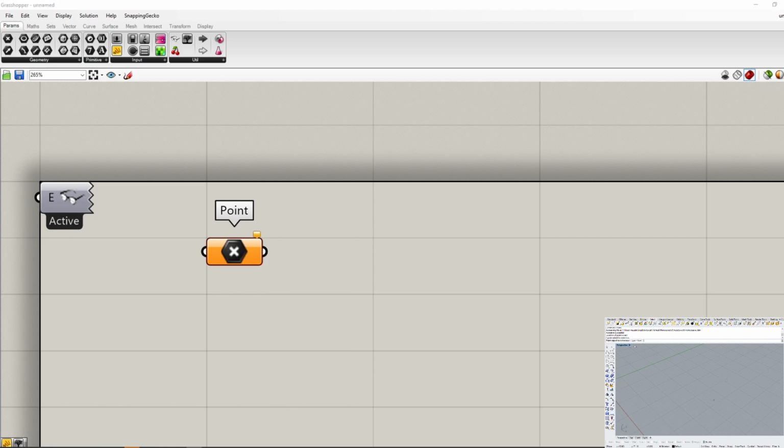And you'll notice in Rhino you have some options about how to bring in point data. I personally prefer it to be set to object, so I'm just going to select the object to reference. And voila, we have a point. Now, I want to prove to you that there's a point in there in some sense. So I've got a point component, it's gone white, so it doesn't have any errors or warnings or messages of any sort, which is great.